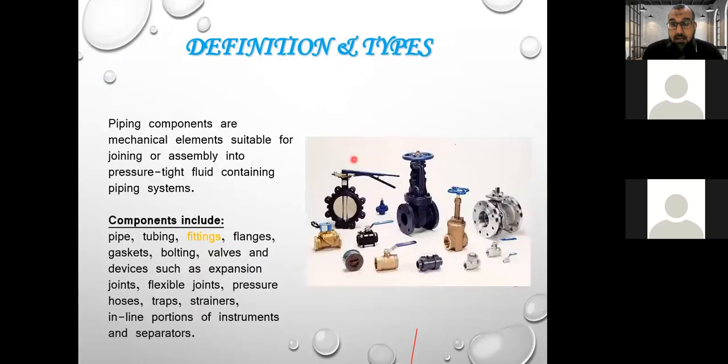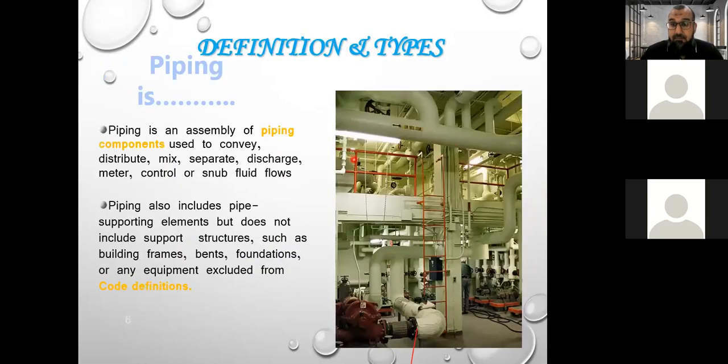However, there is piping, not just pipe. Piping consists of pipe and other fittings like these elbows, tees, and connections between pipes. To connect pipe to pipe, you need connections. This connection is called a fitting. This fitting with the pipe is called piping. And this piping, which is connected to certain equipment like a pump, compressor, or heat exchanger, is considered process piping.